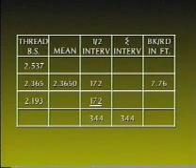Another method for taking 3-wire differential level notes is shown in your workbook using a meter rod. In this example, the notes are going down the page. Notice the 3-wire level notes for a meter rod are taken just like they were for the foot rod. The reference on the notes to the back of the rod means a foot graduation tape on the back of the rod is shot as a check on the readings for the front of the rod.